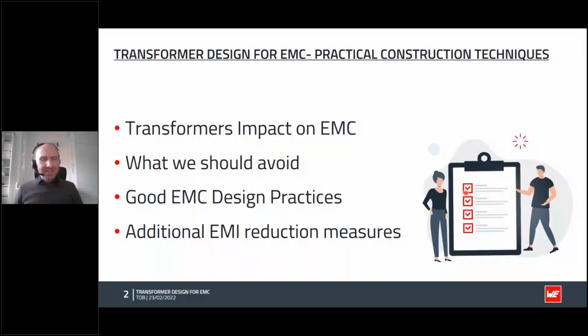So magnetic components are at the heart of every power supply. And when we also need to isolate the secondary side from the primary, we need to use a transformer. Today we will look at how the transformer impacts on EMC and what we should avoid when designing our transformers so that our EMI is minimized.